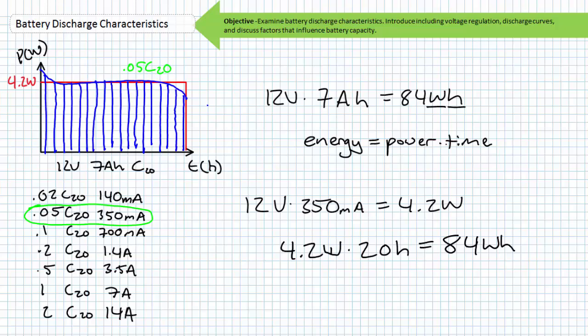The nominal voltage and nominal capacity of the battery is basically a rectangular approximation of the energy content of the battery. And if you're reasonably spatially aware, you should realize it's not that far from the truth. The approximated rectangle is including energy content that isn't delivered at the end of the discharge period, however, neglects to account for energy content that is delivered at the beginning of the discharge period.